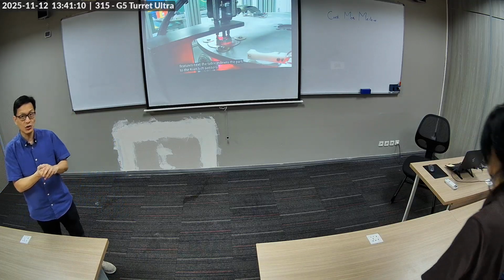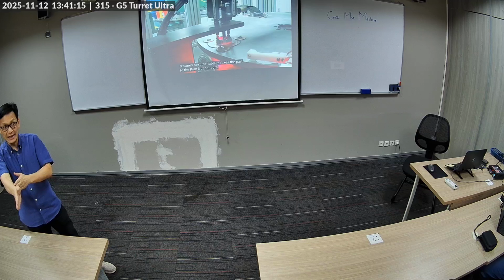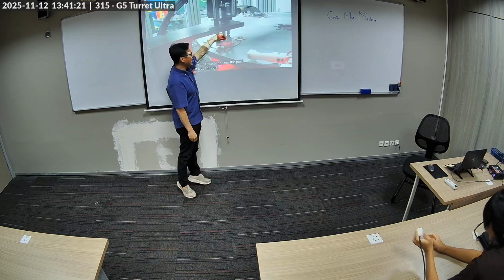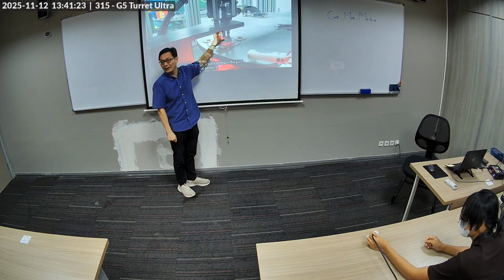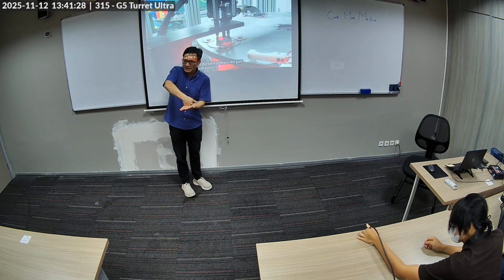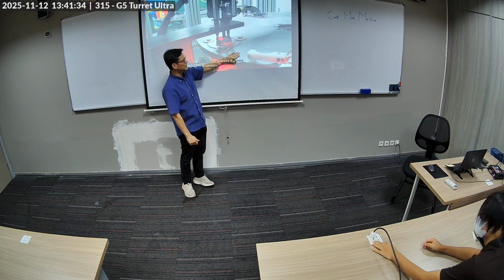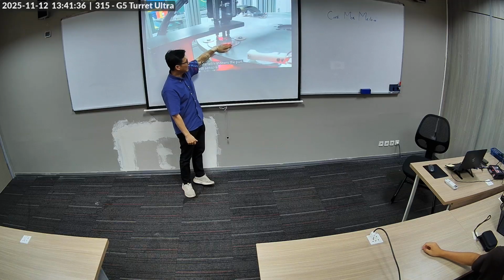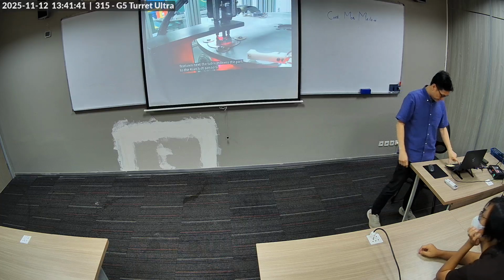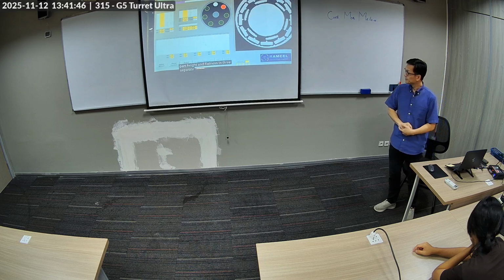Now, an LVDT is also detecting this displacement, but not angular, it's linear, okay? So this actuator comes down, and the extension of that distance is being measured. By touching it that way, now you know the height of it, because you know where this is located with respect to the table. So you have that distance measurement, and that's how you measure the thickness, to detect the part height and flatness in 3 separate locations.